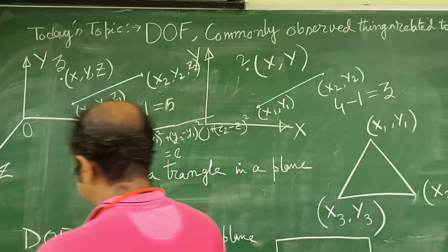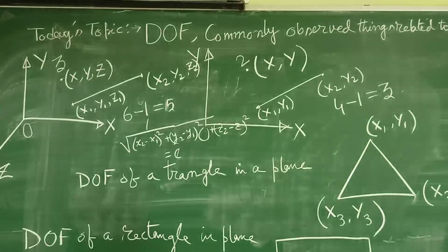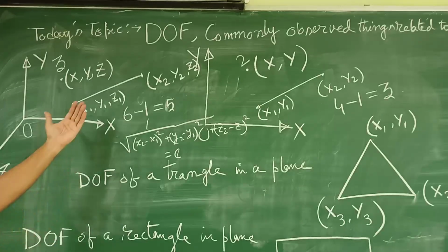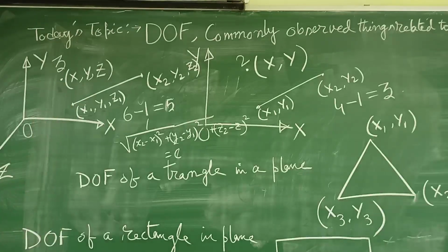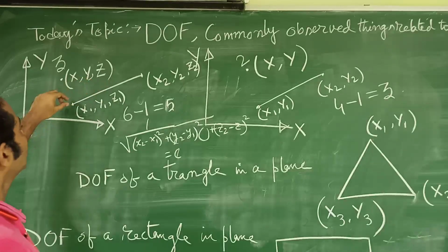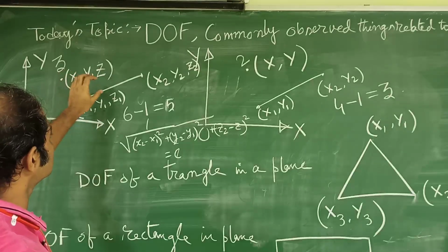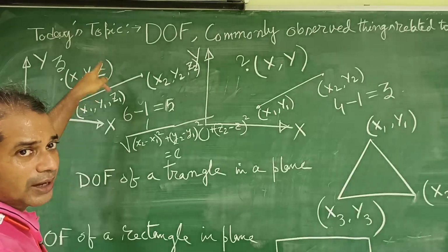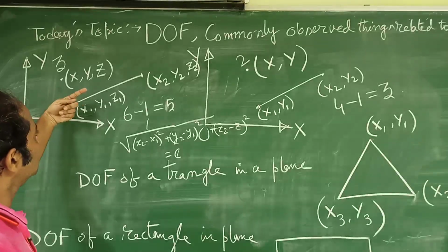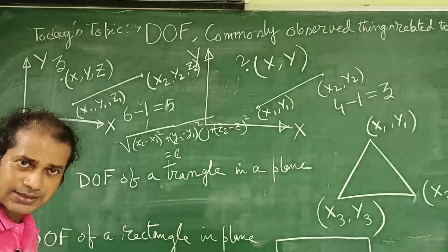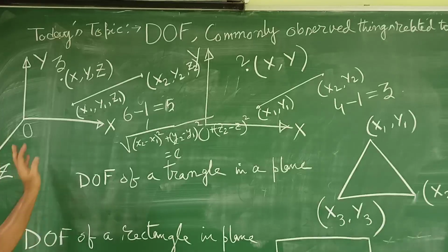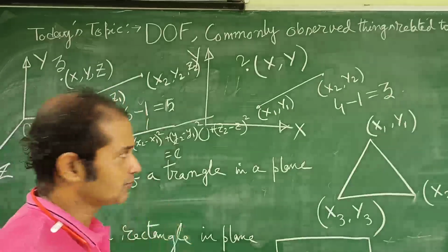Now let us identify that in a physical way. This straight line can translate in x, translate in y, and translate in z. So we got these 3 degrees of freedom. Now this straight line can rotate. Let's choose another coordinate system. It can rotate about x and about y, but the rotation about its own axis is immaterial because it has no dimension. So you are going to get 5 degrees of freedom.